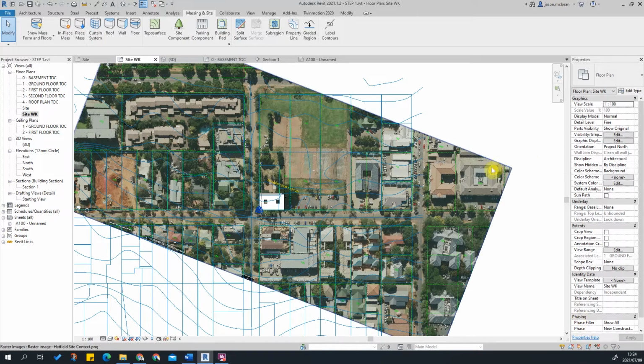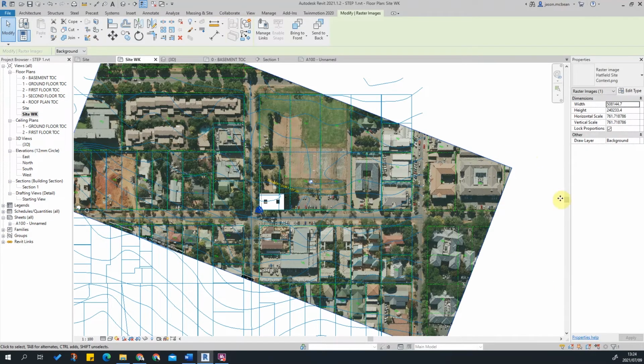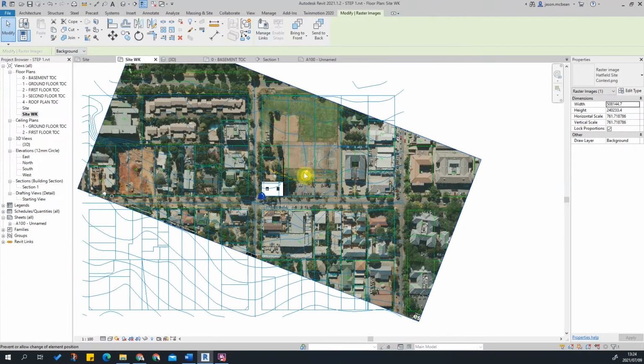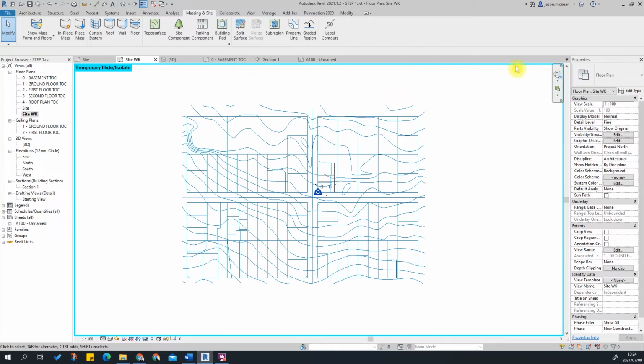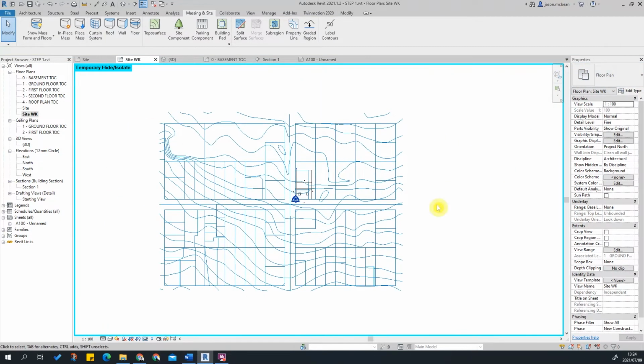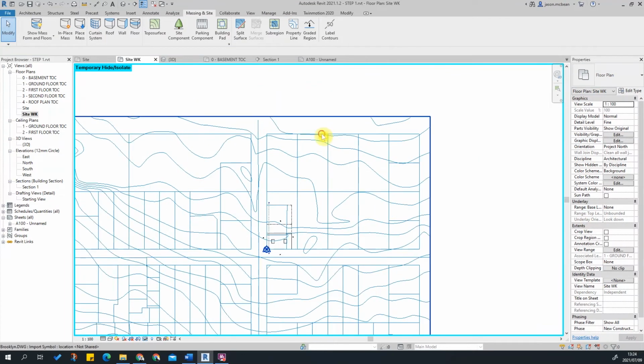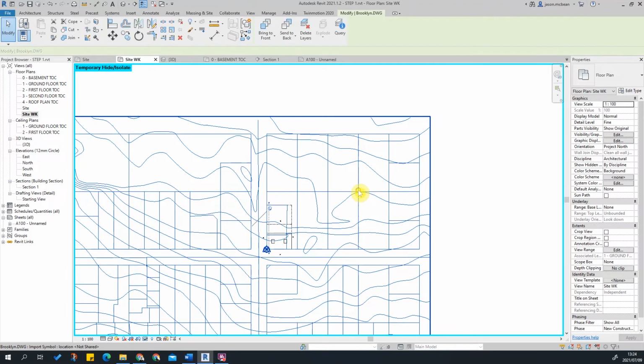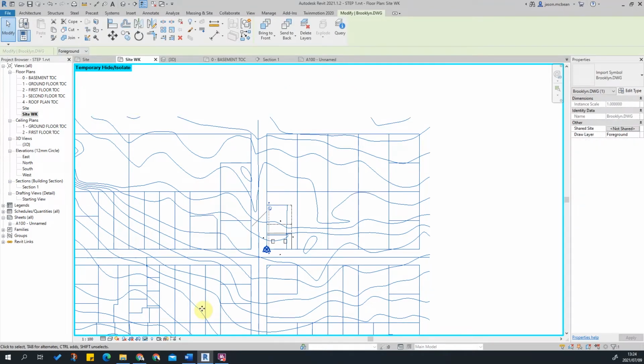It's another way to manage items in your drawing view. Okay, so pin it, and then you can simply use the glasses icon, which is your temporary hide and isolation. So I'm going to hide this element. You'll notice that you'll get a blue frame around the current working window that indicates that something is currently being hidden. I've also got this information from the AutoCAD file, which I'm also going to hide. So you can do the same step. You can simply just say hide element.